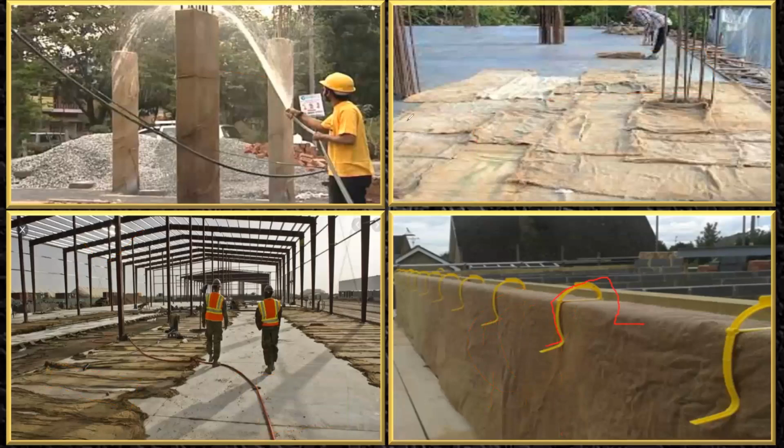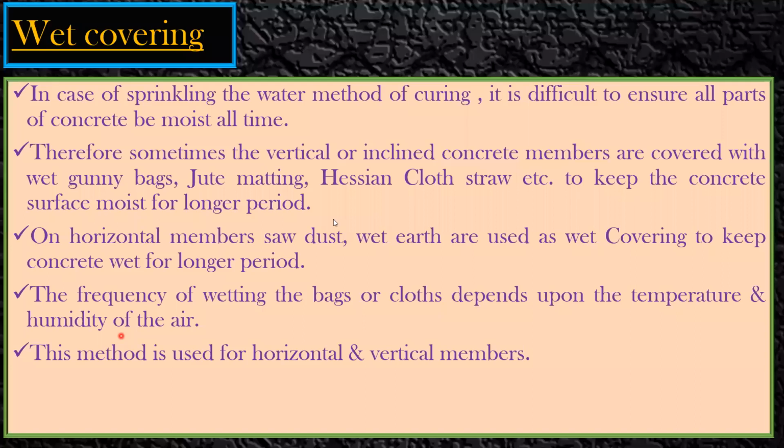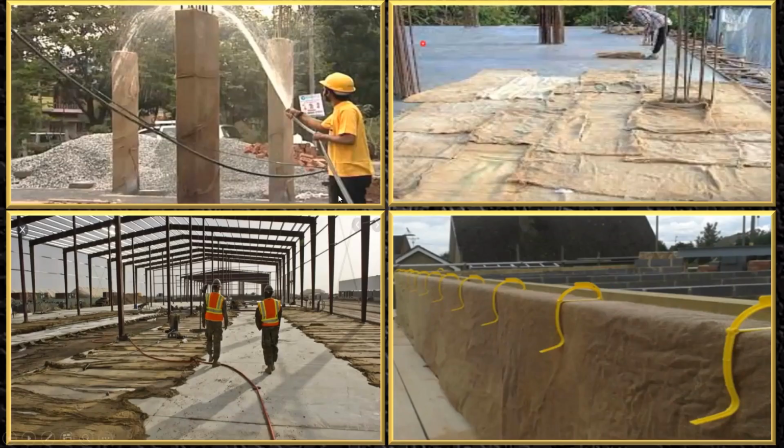So these are the different ways of curing, and based on the requirement, we'll make use of them. Yeah, so that's it. Also, there was one more point about the gunny bag. Sawdust and wet earth are also used as a wet covering to keep the concrete wet for a longer period of time. Sometimes, let us say on the slab, we'll sprinkle the sawdust. We have seen what sawdust is. It is a waste which we get from the manufacturing of plywood and all, right?